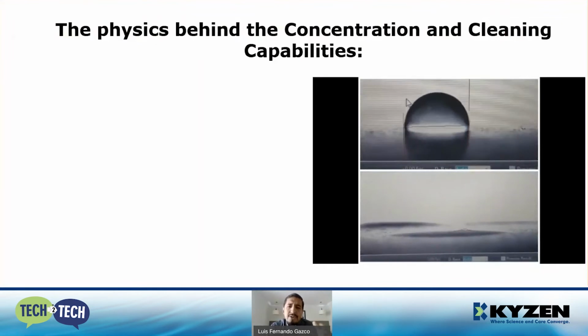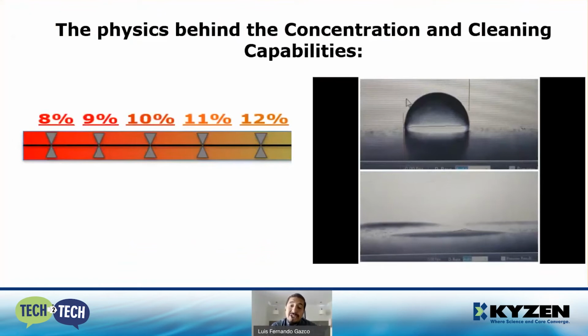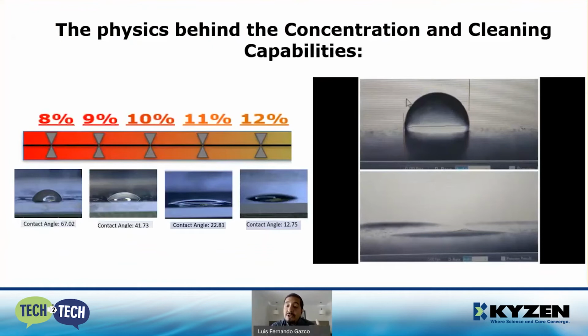Cleaning agents allow water droplets to penetrate those small distances underneath critical components, enabling them to get in direct contact with the flux residue and dissolve and remove it completely. Basically, it flattens the droplets. As concentration percentage decreases, water droplet height increases. Keeping concentration in the recommended range means maintaining the liquid's ability to penetrate and clean.